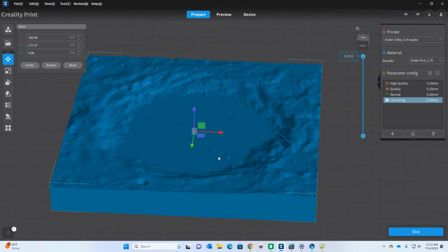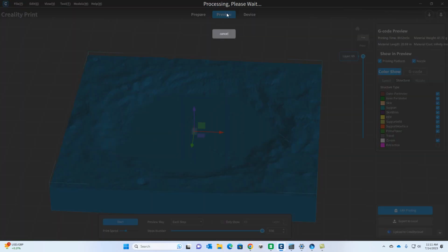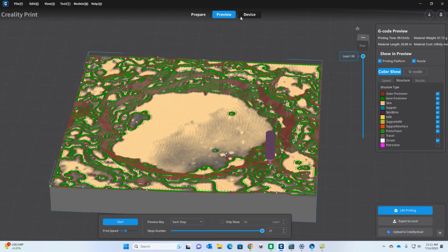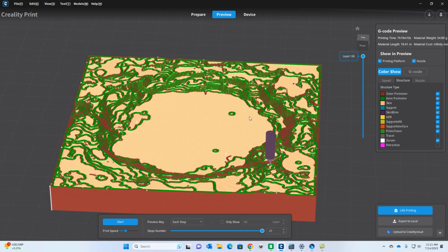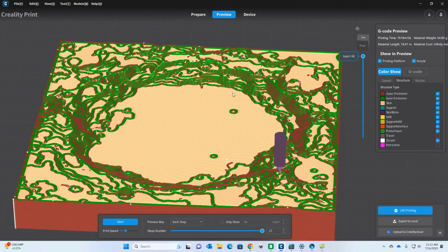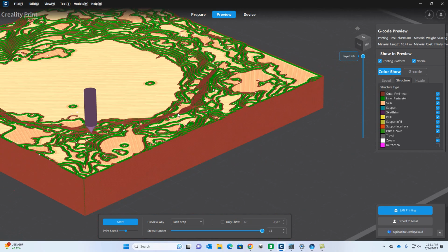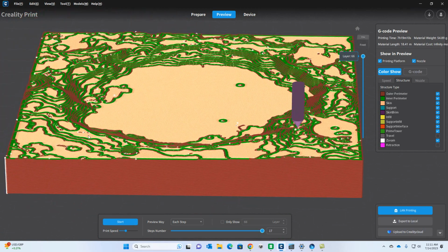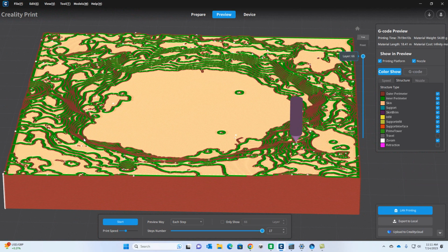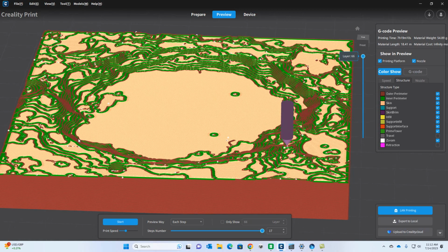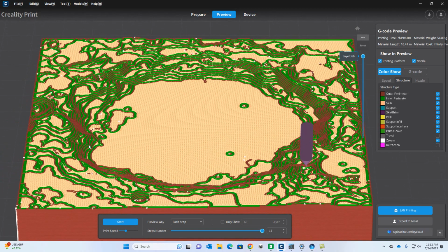And again, this is one here where the resolution could be a little bit higher if we zoomed in a little bit more, but by the time we actually go ahead and slice this, some of that issue isn't as big an issue anymore, because the 3D printing will just naturally end up making the topo layers. You don't want to get much more detail than the thickness of your slices anyway, or you're really not going to benefit from it.